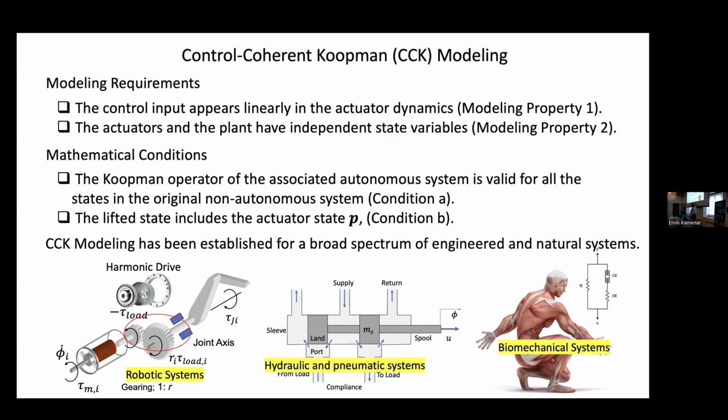Due to the compressibility of the fluid, it has some compliance here. And then on the actuator side of the dynamics, in terms of the spool dynamics, having a constant mass ms and then some magnetic force applied to it, basically forming the linear equation where the control appears linearly.